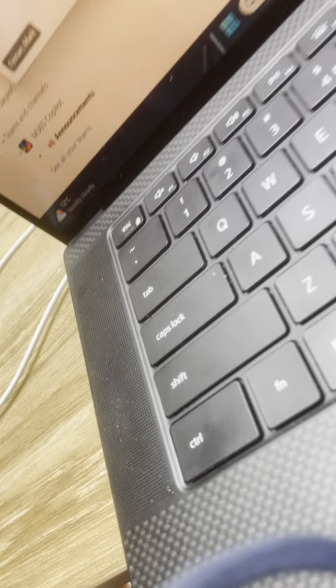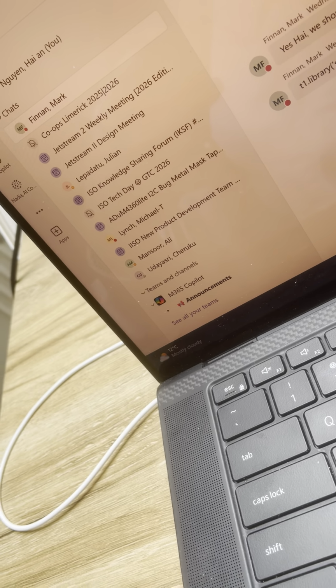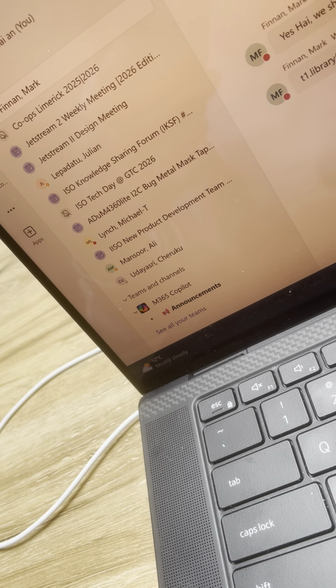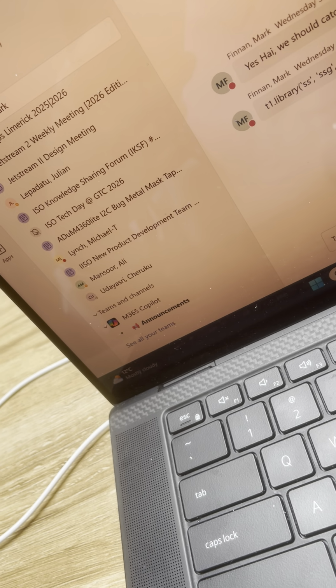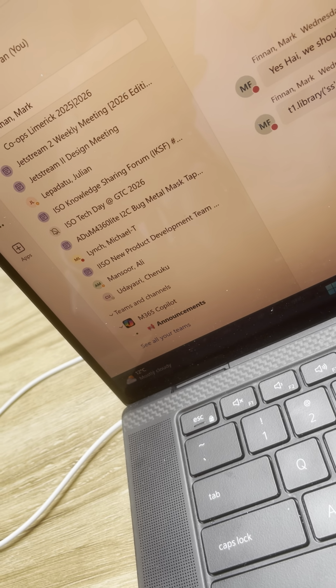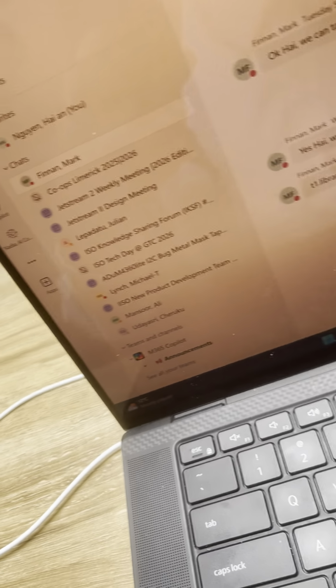Sounds like you're getting on well with the LDO. You got it stable anyway, I think. Yes, I got it stable in the DC sweep. For the AC sweep, I got only around 47 degrees something. That's still good, yeah, that's fine.